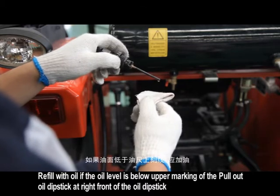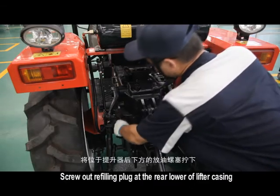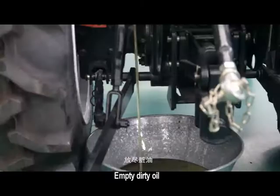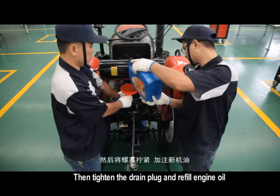When replacing the lubricating oil, screw out refilling plug at the rear lower of lifter casing. Empty dirty oil. Then tighten the drain plug and refill engine oil.